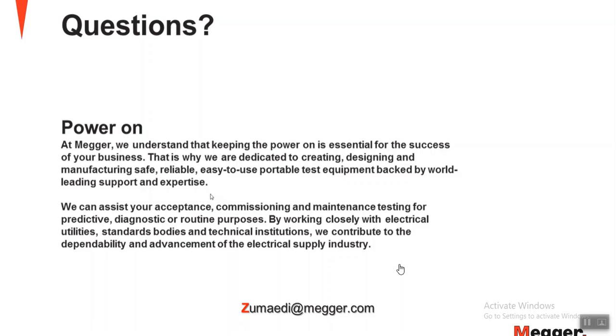For the slope method and other methods, I believe it may be in IEEE 81. Yeah, the standard for grounding testing is IEEE 81. But as far as I know, it only refers to the fall of potential.